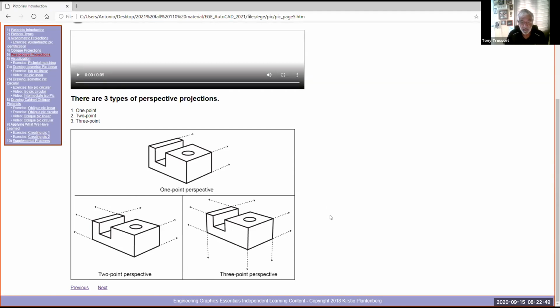Okay, and you can actually draw in AutoCAD. You can do these. You just create a vanishing point to the left, a vanishing point to the right, and then all your height of your object is here, and then the depth of your objects, or the length, whatever you want to call this side, and then the depth is here. And then a 3-point means you have a vanishing point down here, a vanishing point to the right, a vanishing point to the left.